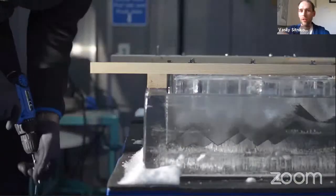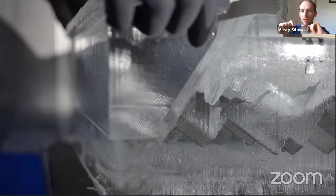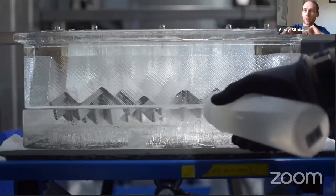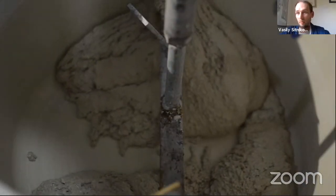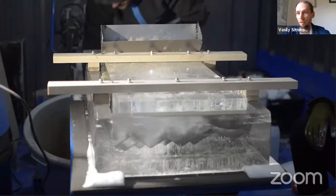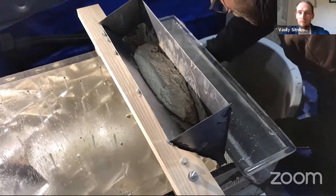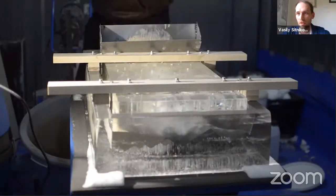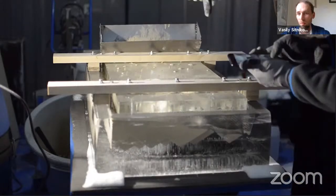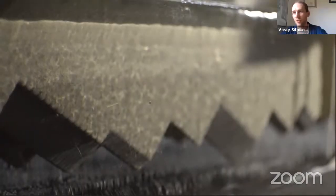And as you see, the top part is suspended on bolts. These bolts are basically dipped in water and then put in the slot so that they fuse into the ice and can perform quite well structurally. And the concrete is mixed, and as I've mentioned, it's a very thin element, so it requires surprisingly little volume of concrete. The development of the mix resulted in a very workable mixture, which can fill even very complex geometry when fed from one side of the element. It just fills all the volumes like water would do.